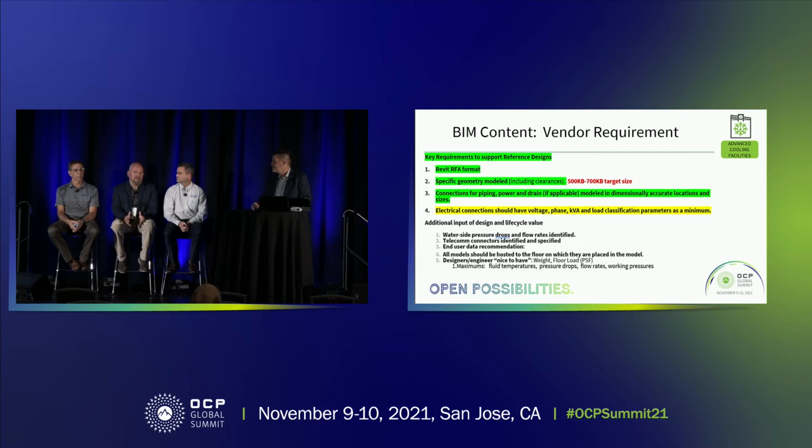It's way too detailed. It was just a straight export from their solid modeling program, and every little washer is being rendered. I've seen every single thread on every bolt rendered. And the other problem is that the dimensions are wrong, or they didn't pay any attention to that. They spent all their time making it look good, right? That's not what you're looking for when you're doing BIM modeling. You're looking for overall dimensions, accuracy on where the connections are, and the different types of systems: water, power, network communications, all that can be put into these models.